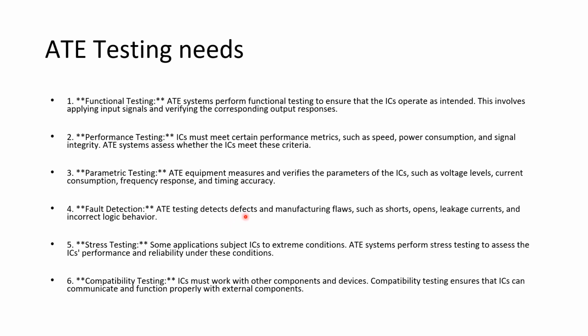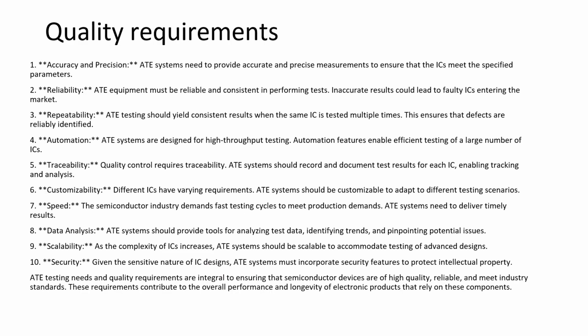Fault detection can detect manufacturing defects, shorts, opens, ATPG tests. You can run stress testing and SCAN tests. Compatibility test: you can check whether your device is compatible with other standards or not. Accuracy and precision: you can check how accurate and precise the parameters are against the specifications you specified, right? Reliability you can check. We already spoke about that.